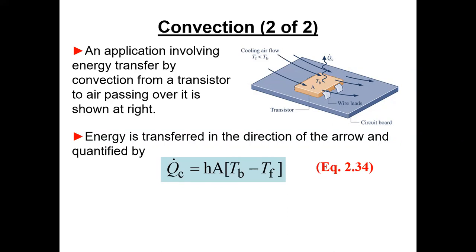Now there are correlations. Well, you can find tables for it, but h's are tough because of just a difference in surface roughness or something. If you do a correlation, you've got a very well-defined fluid velocity profile over that surface.